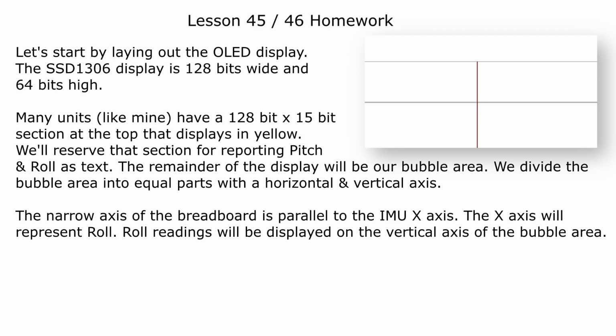The SSD 1306 display is 128 bits wide and 64 bits high. Many units, like mine, have a 128-bit by 15-bit section at the top that displays in yellow. We'll reserve that section for reporting pitch and roll as text. The remainder of the display will be our bubble area. We divide the bubble area into equal parts with a horizontal and vertical axis.